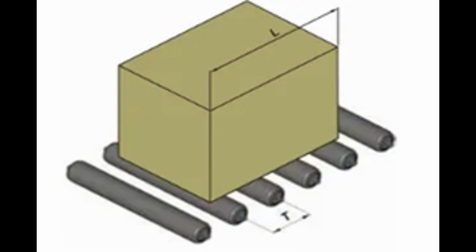For slender goods with large flexibility, the deflection of the goods should also be considered. The deflection of the goods on a roller spacing should be less than 1/500 of the roller spacing, otherwise the running resistance will be greatly increased. At the same time, it is also necessary to confirm that the load of each roller cannot exceed its maximum static load. This load refers to the evenly distributed load without impact. If there is a concentrated load, it is also necessary to increase the safety factor.